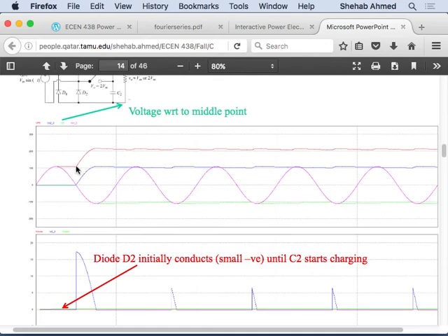In the second half cycle, the circuit before was doing the same: in one half cycle, you were charging one and discharging the other. So here I'm charging this other capacitor in the second half cycle, and they add up to twice. And they both are discharging until when?